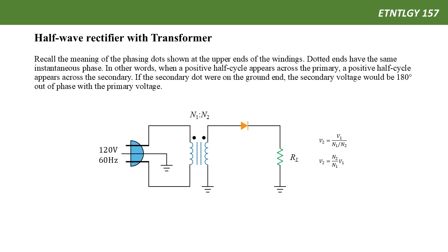On the primary side of this transformer, the inductor connects to the positive and the negative terminals. On the secondary side of this transformer, that inductor connects to a diode, and then the diodes connect to a load resistor to ground. The reason is that we use the transformer to reduce that 120 volts to a smaller voltage. That smaller voltage can go through the diode without burning the diode, and then the voltage goes to the load.